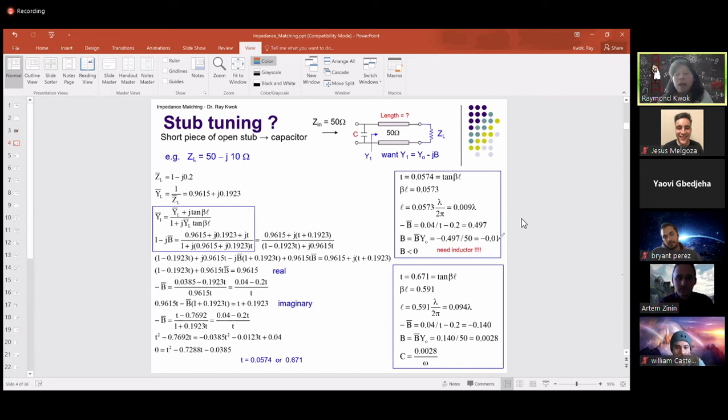At that location, because we know what L is, I can drill a hole, make a little tiny inductor and stick it in there. We can do that. But more than likely, for the circuits that we have, no one is going to do it. We just say, okay, that's not the best solution. The second solution is a lot easier to achieve without drilling holes and all that. So in practice, no one would do the solutions on top.